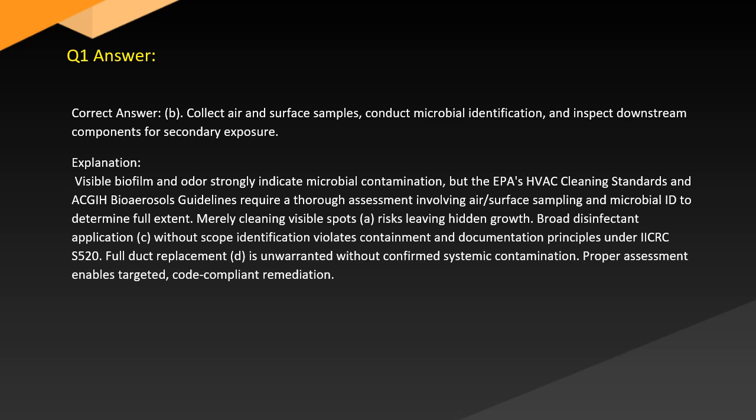Merely cleaning visible spots, A, leaves hidden growth. Broad disinfectant application, C, without scope identification violates containment and documentation principles. Full duct replacement, D, is unwarranted without confirmed systemic contamination. Proper assessment enables targeted, compliant remediation.